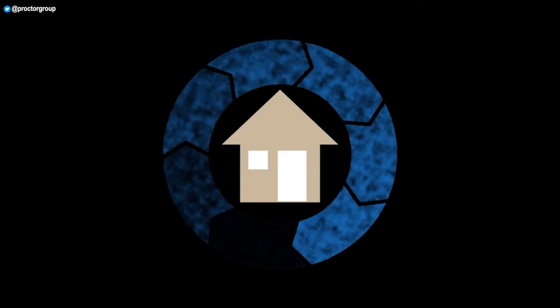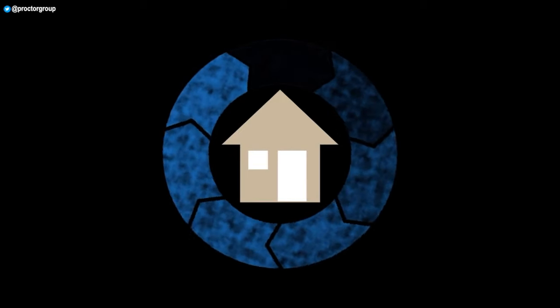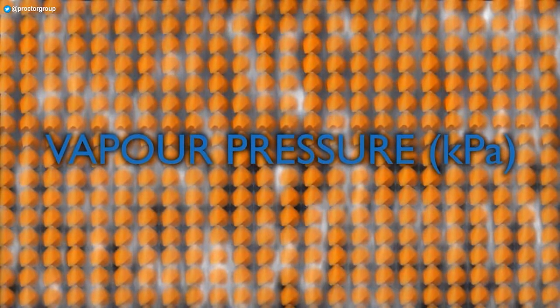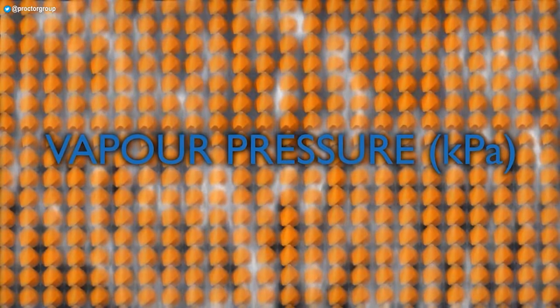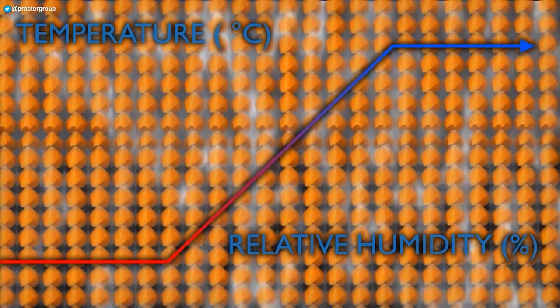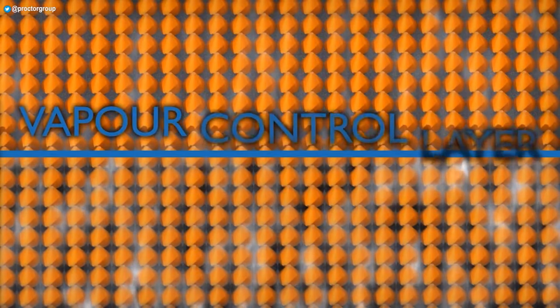As well as understanding the sources of moisture, it's important to understand how moisture moves around the building. Vapour diffusion is the movement of vapour molecules through porous materials because of vapour pressure differences. These vapour pressure differences are created because of temperature and humidity differences in the air on either side of the material.